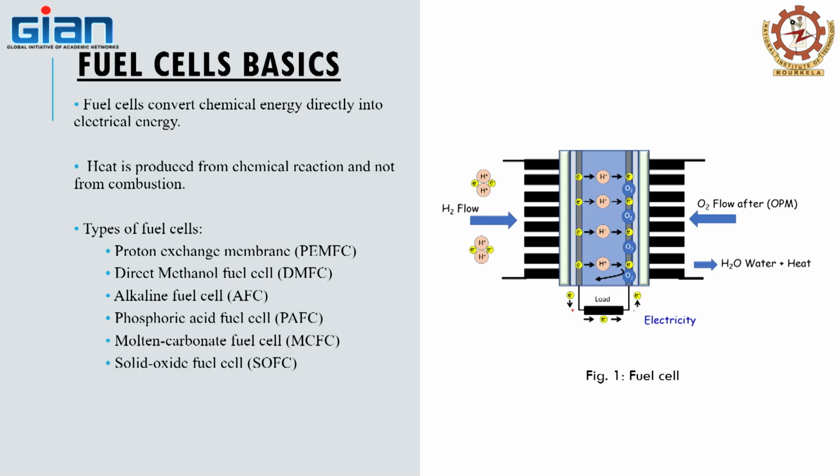Definitely we have seen that this voltage is 1.23 volt theoretically, and it goes down to 0.7 volt, because of which we need to connect them in series in order to increase the voltage level for our practical purposes. And here also one thing I explained that day, that the power delivered by this fuel cell depends on what the rate of fuel flow to the fuel cell is.